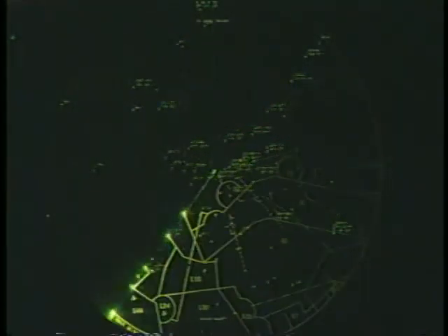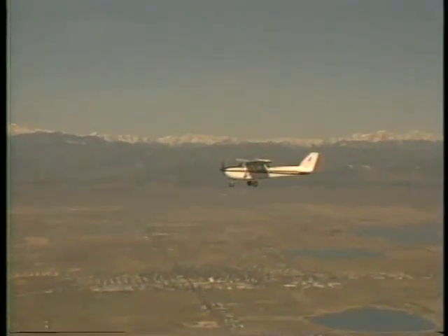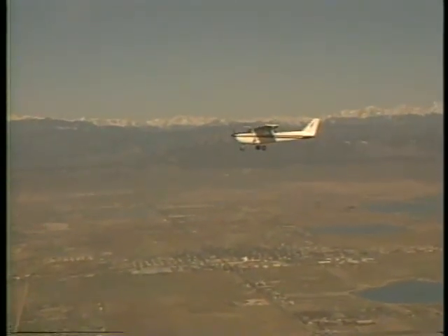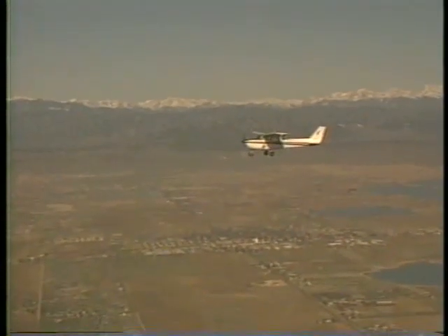"Cessna 740, ident." The controller will let you know that he has identified your aircraft and will provide you with appropriate instructions. "Cessna 740, radar contact. Report reaching 7,500." You are strongly encouraged to use VFR radar services when available because of the added safety provided. The level of service varies with the type of facility. Basic radar service provides participating VFR aircraft with traffic advisories and limited vectoring.